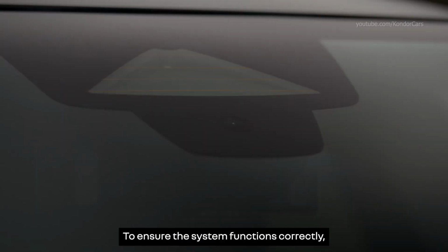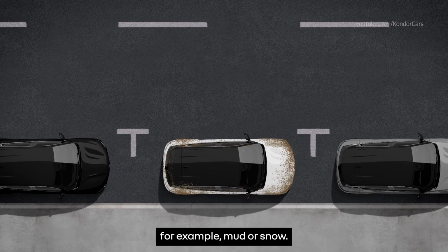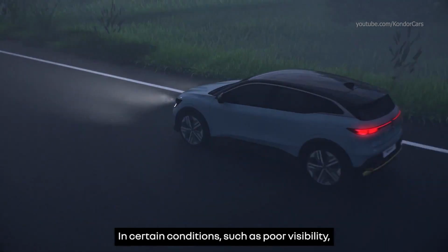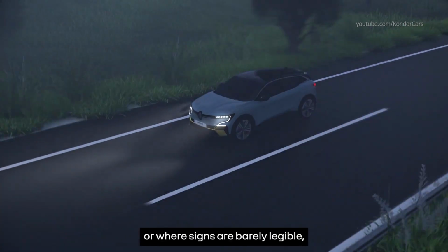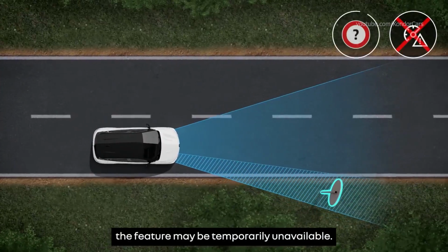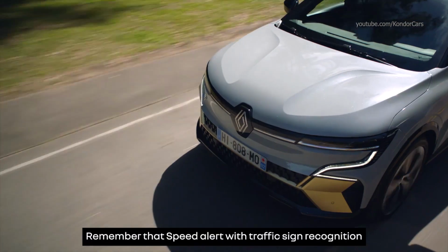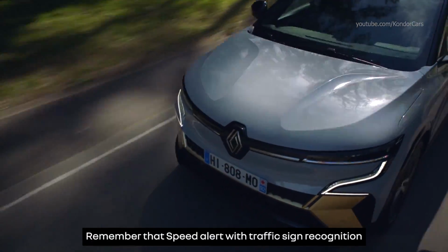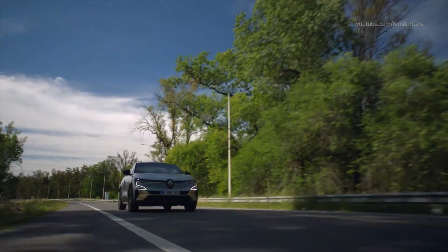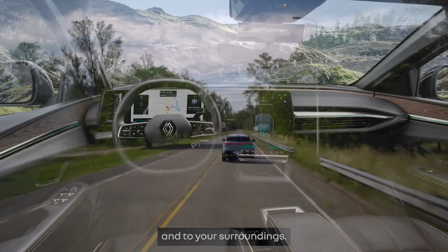To ensure the system functions correctly, ensure that the camera is not obstructed by any dirt, for example mud or snow. In certain conditions, such as poor visibility or where signs are barely legible, damaged or poorly positioned, the feature may be temporarily unavailable. Remember that Speed Alert with traffic sign recognition must not replace your vigilance as a driver. Always pay attention to the traffic conditions and to your surroundings.